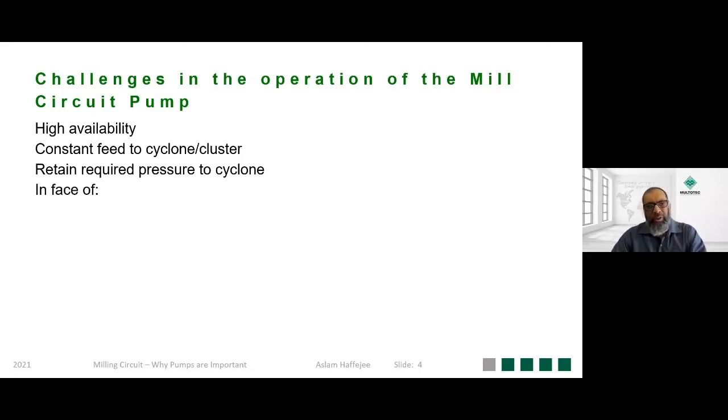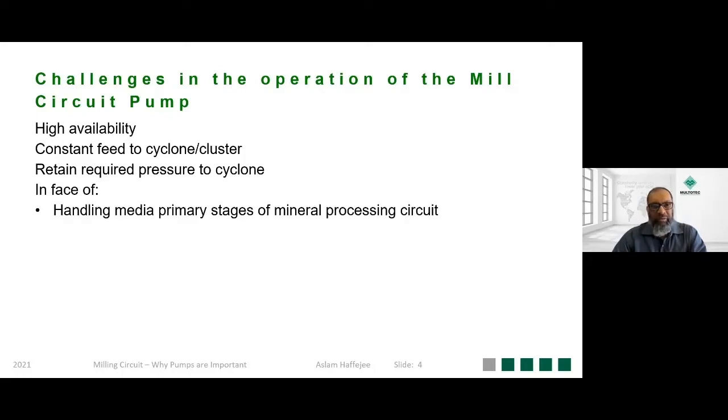It's got to maintain all this in the face of having to deliver media that is at the very outset of the mill circuit or any mineral processing environment. And the material is typically going to be coarse, it's going to be abrasive, and in most cases where people are reluctant to use too much water, you're going to have a high concentration of solids.